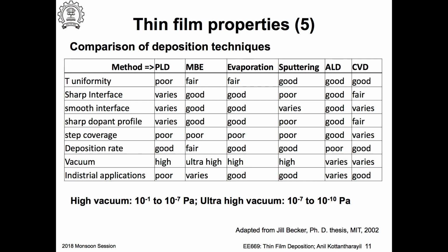So what was this fluctuation? You think it's noise? No, but why did it come back to a high pressure condition and then start going back again, a fairly fast rise in the vacuum? These are some gas that is trapped on the walls of the chamber. Suppose you were depositing aluminum, and when you opened the chamber, some aluminum flaked off a little bit, so some air got trapped inside.